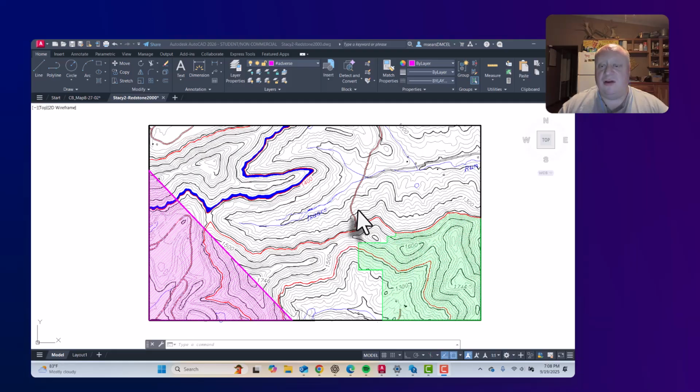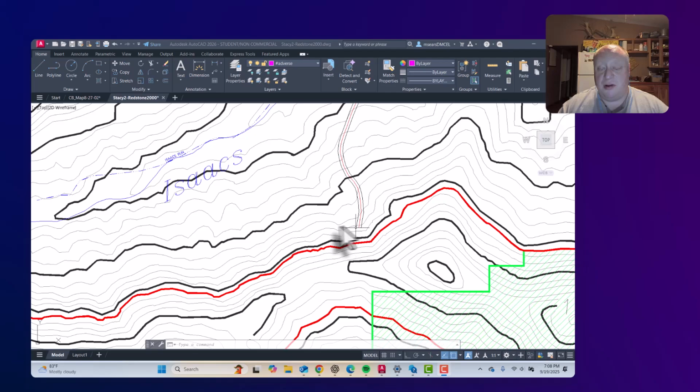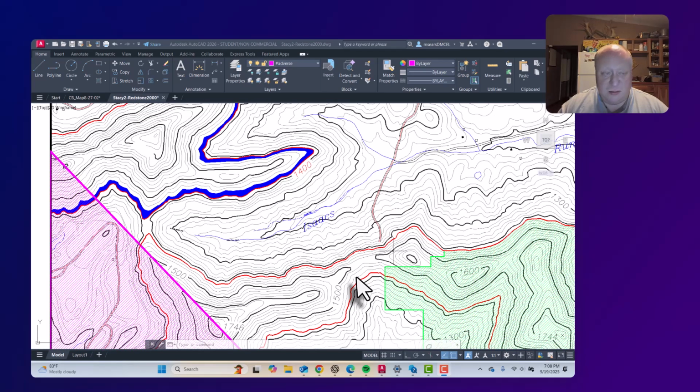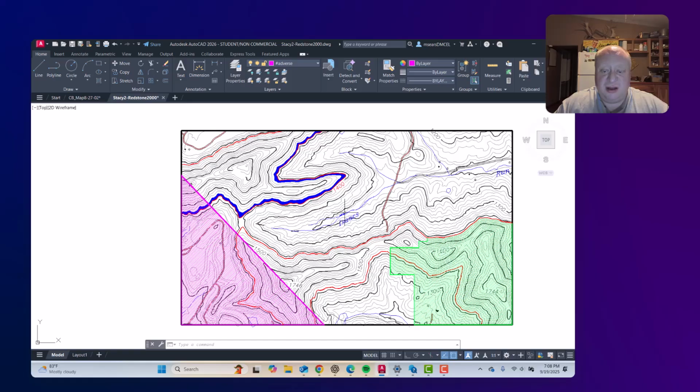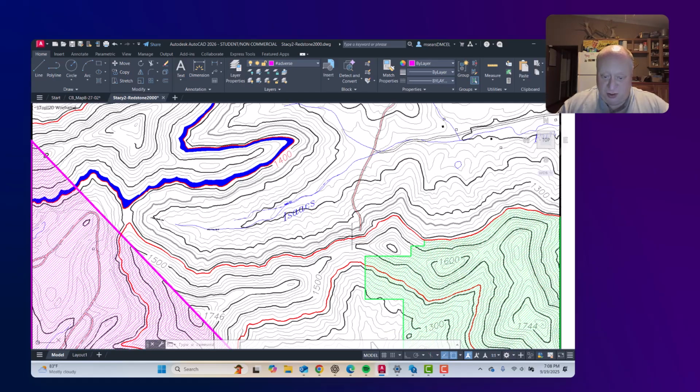But where you're going to access the reserve, you have a road here. It comes to right about this point, almost up on what will be the bench. And so you may initially think, hey, I'm going to start right here. You might be able to. But the first thing you need to know about where you're taking your first cut is, where am I going to put the overburden, the spoil from this, so that I can mine the coal underneath it? So where am I going to store it?